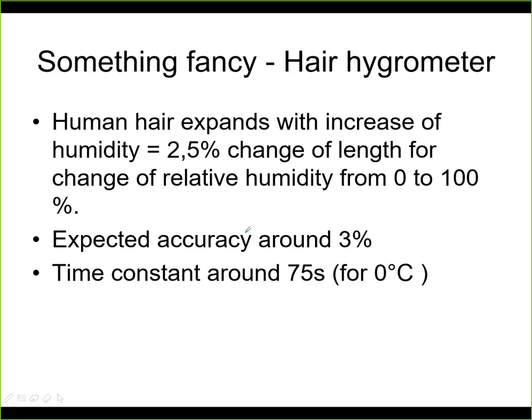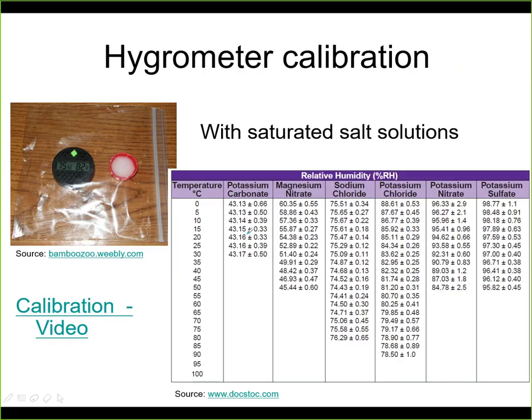But we'll skip this hair hygrometer, and I will just go to the calibration. How to calibrate the hygrometer. The calibration needs to be done in an environment where you have a constant humidity, and this can be achieved with a solution of a saturated salt.